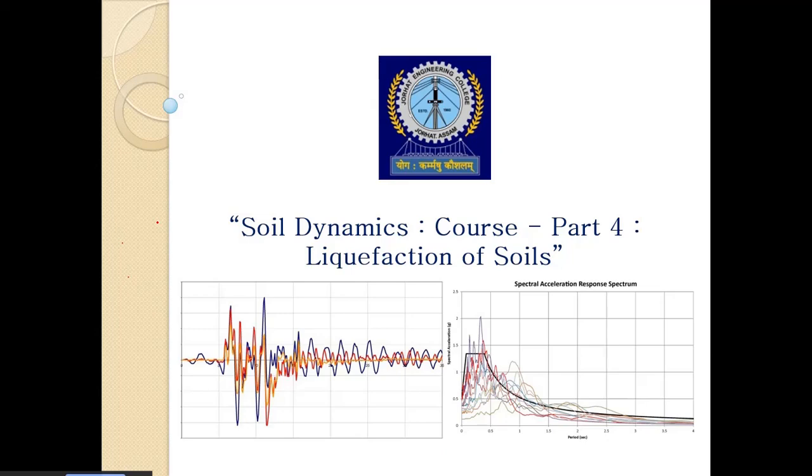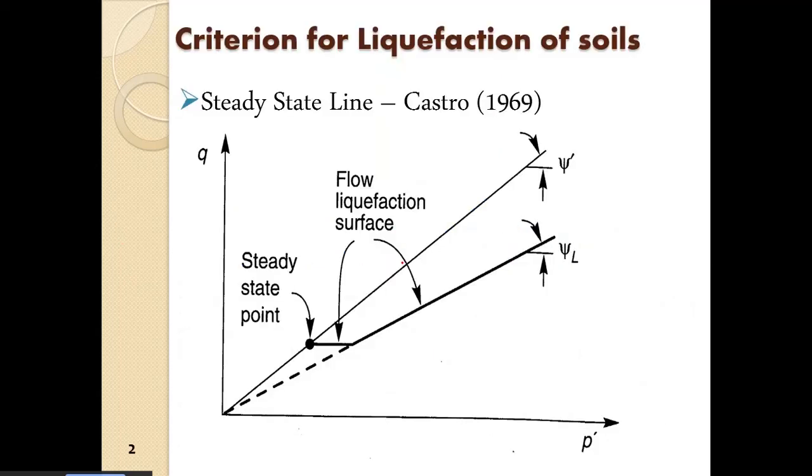Okay, so we were discussing liquefaction of soils, and in the last class we discussed the stress condition that develops in situ, and how we can replicate that in the triaxial test. We also discussed how, when we plot the stress condition with the Mohr circle, the Mohr circle moves with the development of pore pressure during the dynamic loading.